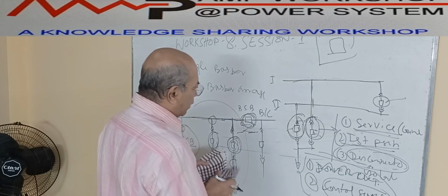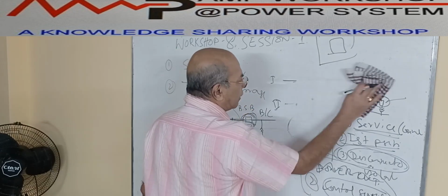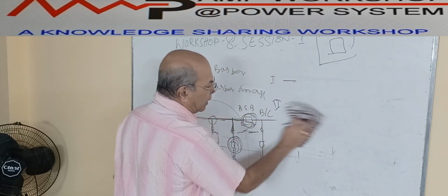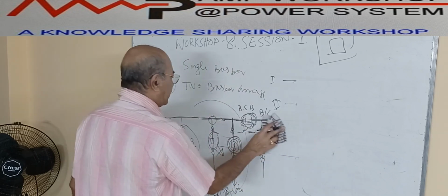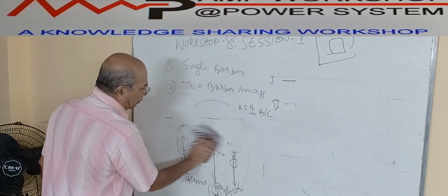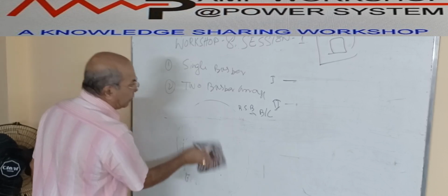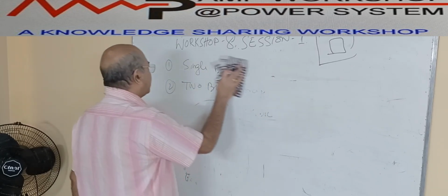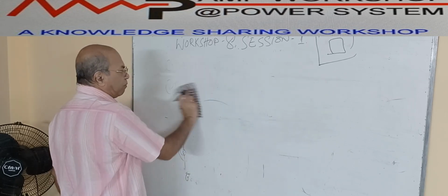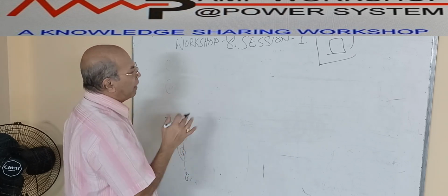So now this is a drawout type switchgear. Now if the switchgear is not drawout type, if it is a fixed type, in that case we cannot get this drawout feature. We cannot get these three positions. In that case, how do we disconnect the power supply, or how do we disconnect both control and power supply? For that, we have an alternative arrangement. We need another power device to obtain that feature. That is what we call a fixed type switchgear, because here the main power components cannot be moved out or moved in. All the components are permanently fixed.